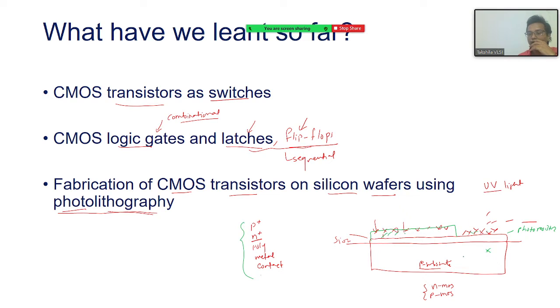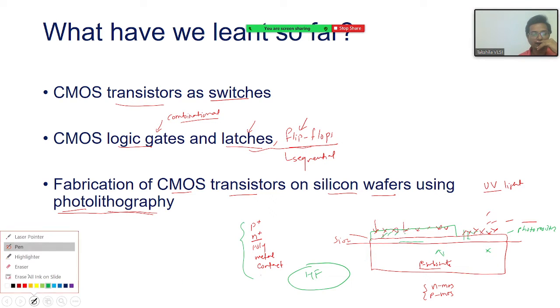So then I put this wafer in the hydrofluoric acid, which will etch the oxide in this region, because you see this is the silicon dioxide, SiO2, right here. If I use the right ink again, this is SiO2, right? So how does the wafer look then?